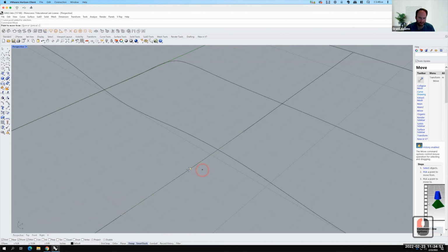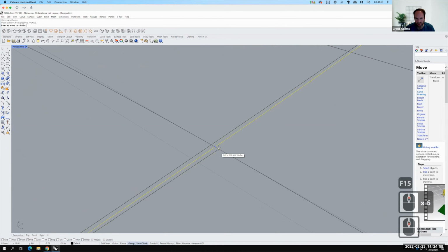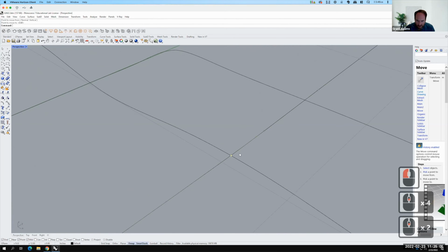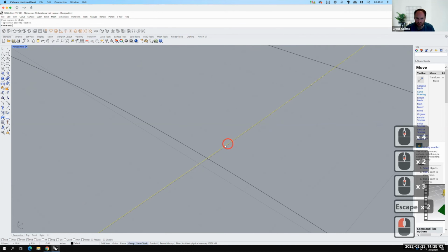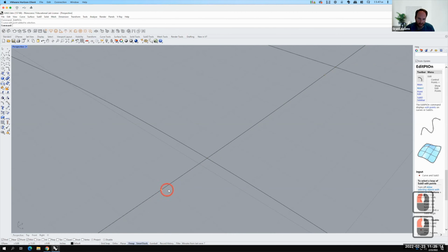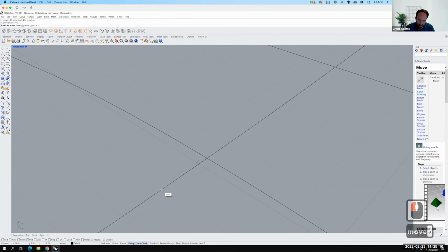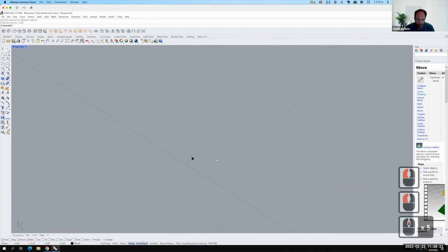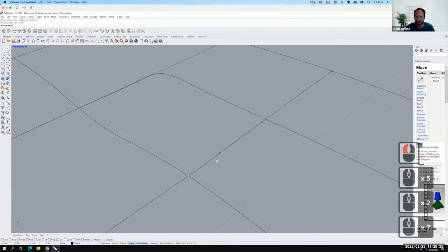There's a point. I can snap to that point, and I have to make sure that that one stays right on that midpoint. And if we zoom in, you can see that they're not quite intersecting. So it's very important that I keep those points on themselves. Actually, sorry, I need to turn the actual control points on. This one, the curve edit points, and I need to move that one because I need to be able to move the exact curve so that they are on top of each other. There it is. So those have to intersect. Now I can manipulate these other points.